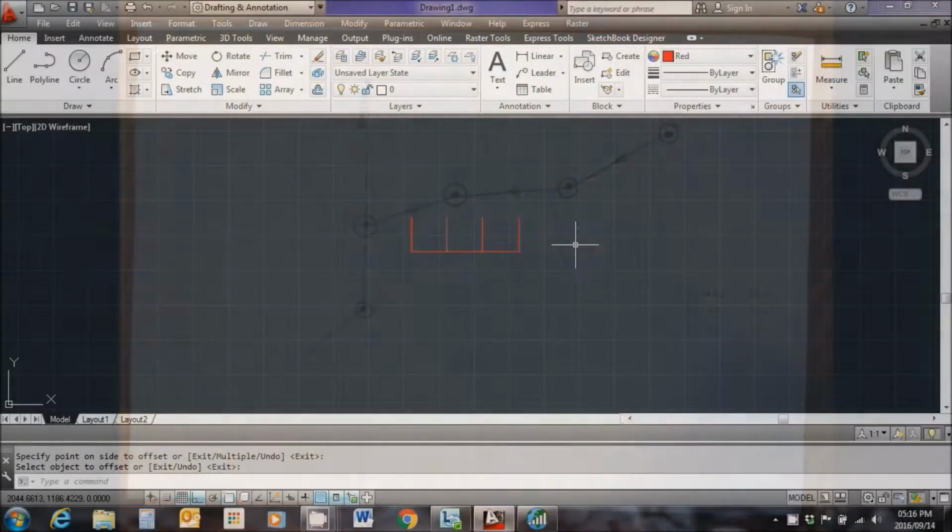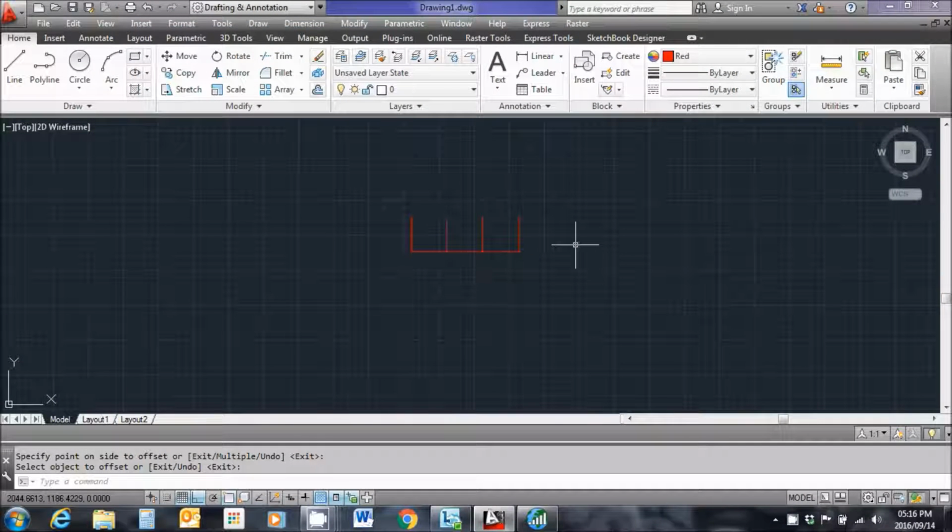Okay, so the next part of the video is going to be about creating the ground longitudinal section from manhole B1 to manhole A6 on our sewer line. Now, in order to do this, I need to be able to pick up the ground levels at specific points along the length of the pipe, and I'm going to start by finding out the ground level of manhole B1. From the drawing, I interpolate the height to be 90 meters above sea level.